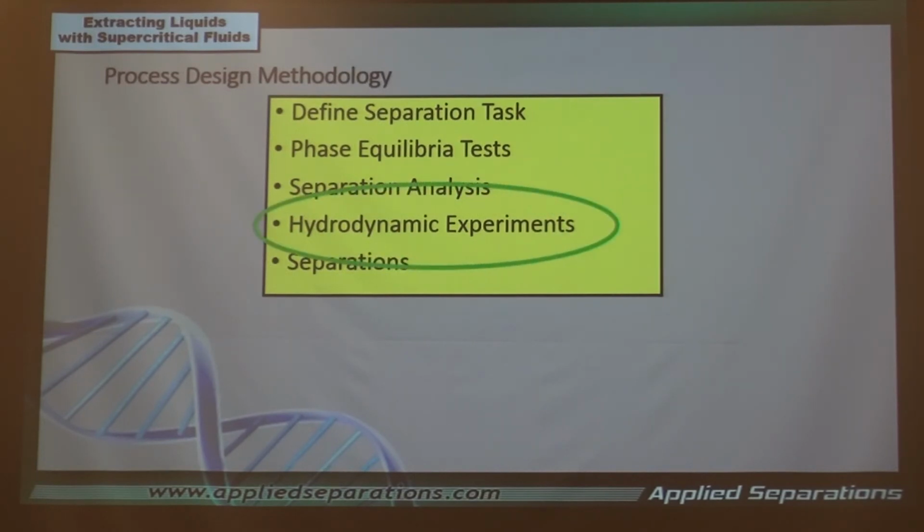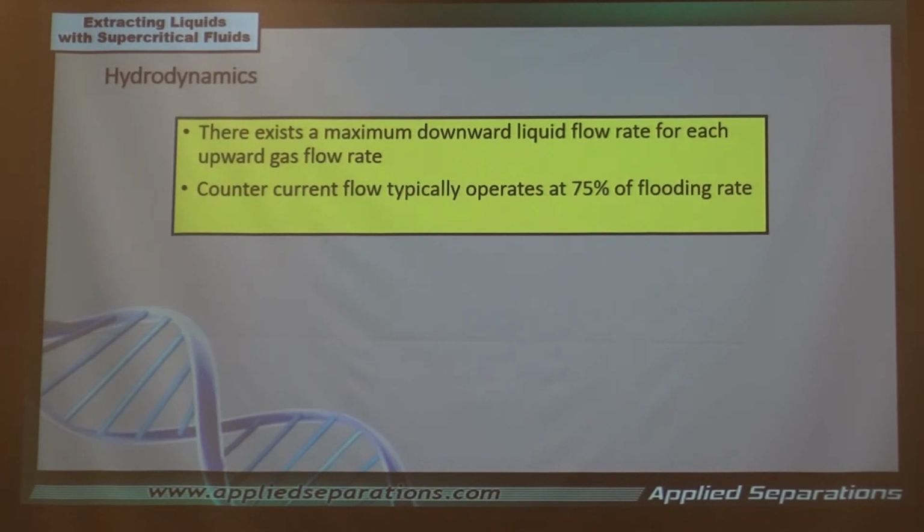this really comes down to conceptually what I just described. We're taking a liquid that is more dense and passing it through the supercritical medium, which is less dense, and then having the solute that is in the liquid pass into the supercritical fluid. Okay?